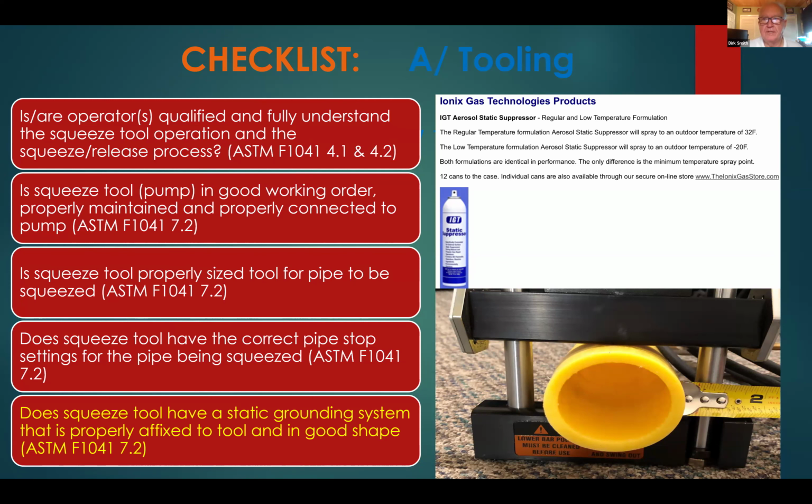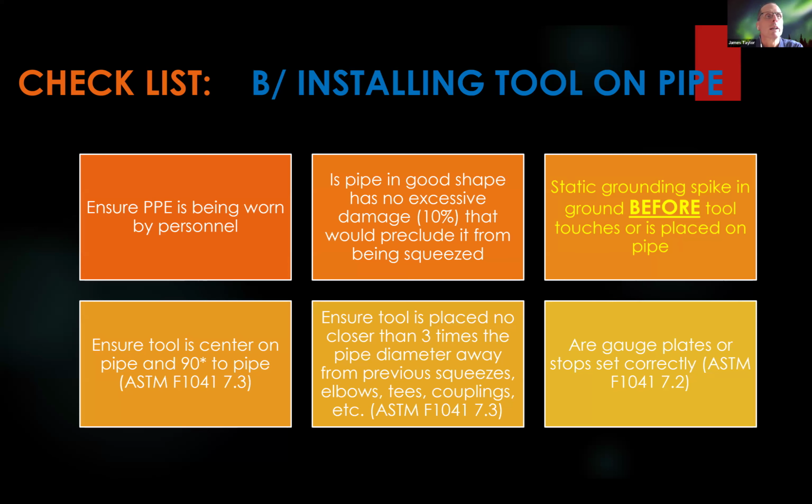No worries. And then next slide. We've got our tooling, and now we're going to touch on installing it on the pipe. So we'd make sure the pipe is clean. We're wearing our PPE. Pipe is in good shape, with no damage that would preclude it from being squeezed. I don't allow 10% surface finish damage, so we don't want to squeeze on anything that's damaged.